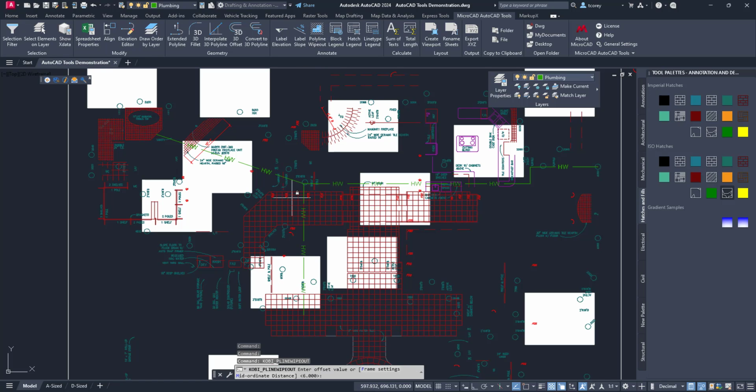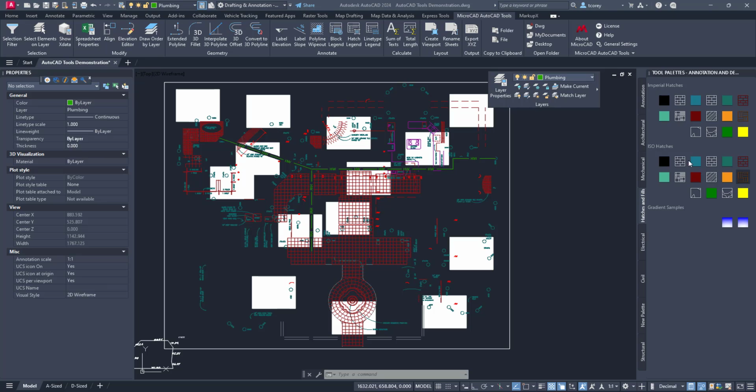Okay, I'll use a wipeout distance. We're offsetting 6 feet total. Okay, which objects to use? Those 2 polylines. Hit enter. So then you see how it ends up giving you a wipeout all the way around.